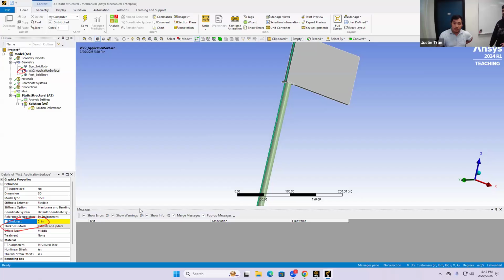Okay. So for this model, I recommend assigning a thickness of 0.01 inches. Or in other words, 1e minus 2. So that thickness is sufficiently small so that, again, it's not going to add any structural strength. But it's thick enough so that problems don't occur. Because what can happen sometimes if you assign this thickness to be too thin, so what I've done in the past for this activity is that I've actually assigned it to be 0.001 inches. Okay, so 1e minus 3.